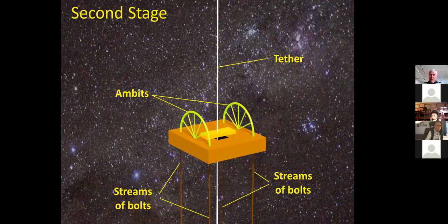And they go around, and in the same way, they create an upward force. Now, you'll see the tether going straight through, but it's important to realize that those blocks there act as a gate, and they support the tether below. And there are, in fact, another pair of gates at the underneath side of this second stage, and we must only ever open one gate at a time in order to hold up the weight of the tether below, because the tether above cannot support the weight of the tether below. So that's how the first and second stages work.